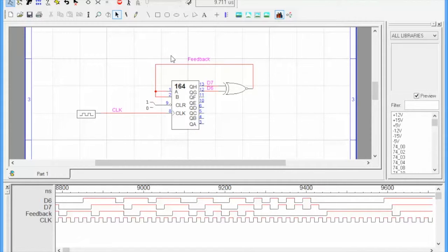And what we'll cover first off is deleting line signals and also deleting devices. So the easiest way to delete a signal is just to select it and hit the delete button. And I'll undo that by hitting Control Z. This is true for devices as well. You just click on one, select it, hit delete, and it's gone. And I'll bring it back once again with the Control Z.